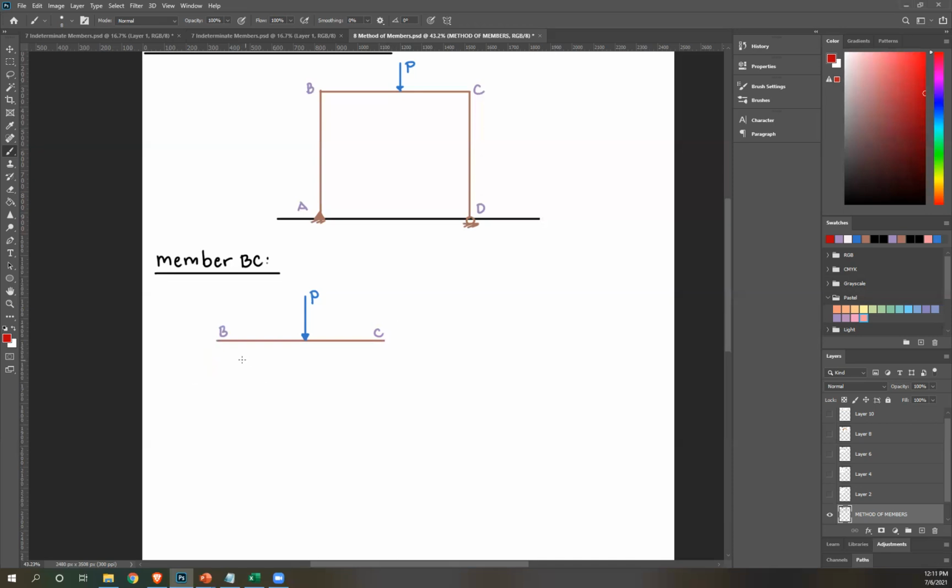And then to simplify that, what we'll do is for 3/4 members, the reactions at each hinge is just vertical and horizontal. And similar to your previous analysis, you're guessing the direction, okay? So we have an upward reaction here. Let's call that BV for vertical, and then this is BH.